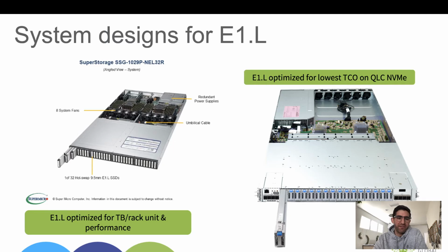And then you can see they have these latches and LEDs on the front, so it's just easily hot plug, serviceable and removable from the front of a server. And this is an example of a Supermicro system with 9.5 millimeter E1.Ls, and there's 32 of them across the front of the 1U. So with 15.36 terabyte drives today that are shipping in the market, this is about half a petabyte in 1U. In the next year, we'll have a petabyte in 1U, so extremely dense solutions for that around EDSFF.